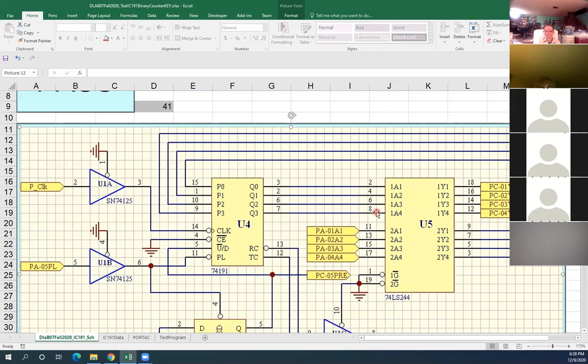Well, in this class, you check the wire, but in industry you can't do that. Yeah, but that's what I'm talking about. The program tells you they read 0 here, but you want a 1. You now fail right here. You go back to pin number 8 and take the measurement. Two things you can get. First, you get 1 on pin number 8. Tell me what you want to do next.